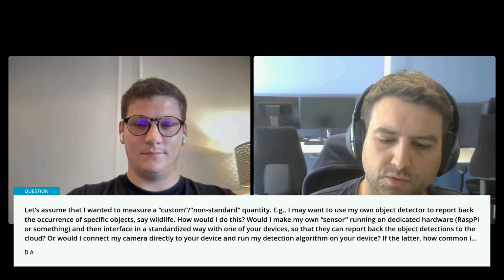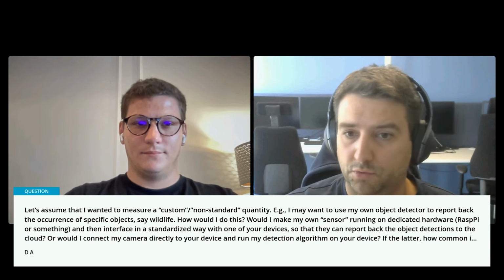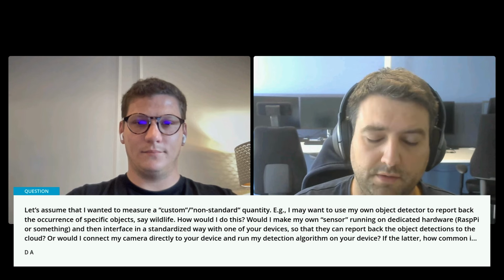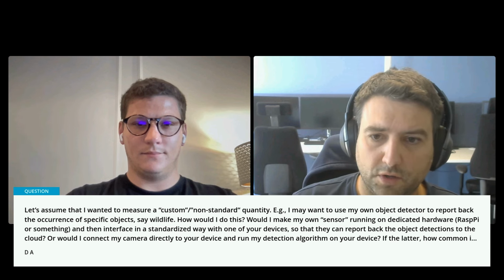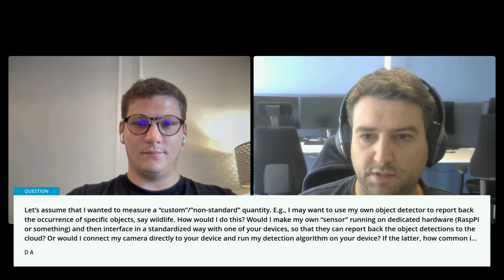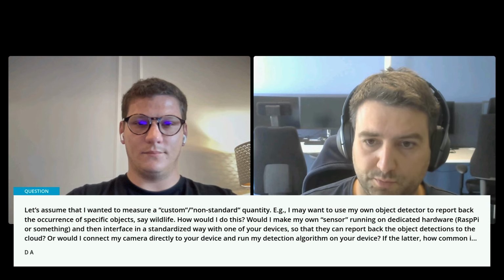And you can do really complicated things, even things like graphics and comms, like what you guys are doing with the backends, right? You have a backend, and you can send data to the blog over UART. You can send data to Golioth Cloud over cellular. You could also send over Wi-Fi. Actually in our SDK we have applications that can be built for both a cellular target as well as a Wi-Fi target. The reason is that the application is just using IP level connectivity, so it really doesn't matter too much if you're using cellular connectivity underneath or Wi-Fi. You can build the same application and really decouple the application from the underlying transport mechanism.